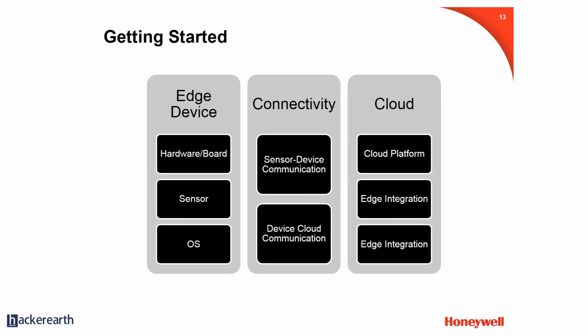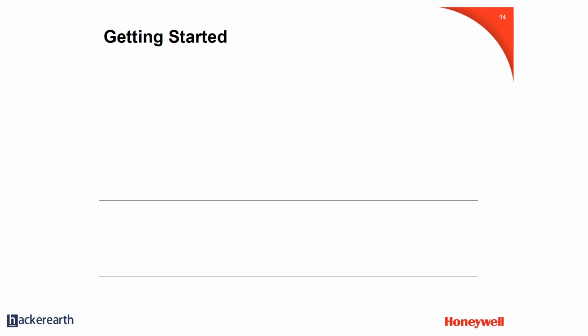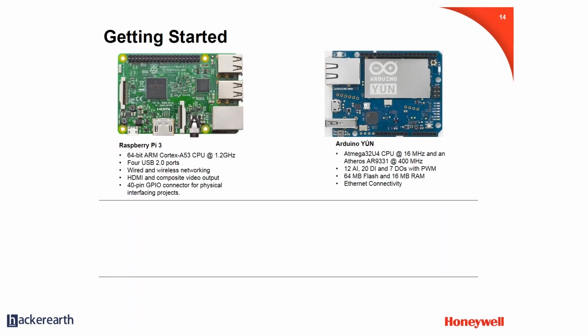Then you have secure boot. When you're booting your firmware, there has to be a check, otherwise somebody can put some malicious firmware and make your device boot. So secure boot ensures that only signed firmware is booted. There is a way to sign the firmware, and the bootloader recognizes the signed firmware and then allows that to boot. So these are some security aspects to consider.